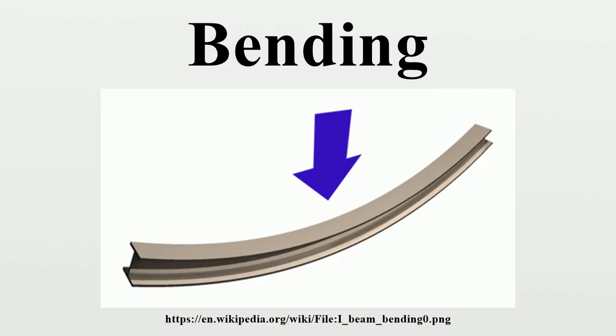The maximum compressive stress is found at the uppermost edge of the beam, while the maximum tensile stress is located at the lower edge of the beam. Since the stresses between these two opposing maxima vary linearly, there therefore exists a point on a linear path between them where there is no bending stress. The locus of these points is the neutral axis.